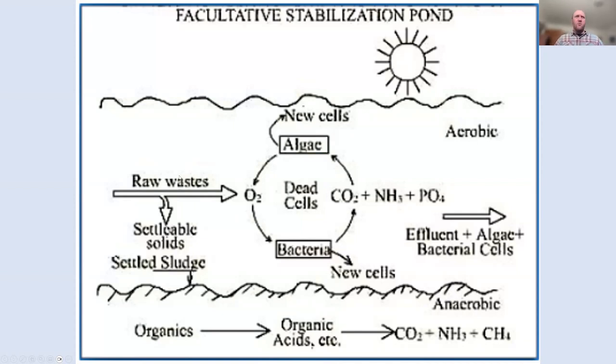And then the aerobic zone is more of the cellular respiration and photosynthesis process. The algae is adding oxygen, the bacteria is using that oxygen, converting this nitrogen and phosphorus into cellular material in their bodies, and it's also releasing nitrogen into the air. I like this graphic because it simplifies things a little bit, a good visual. But it's these processes we just went over.